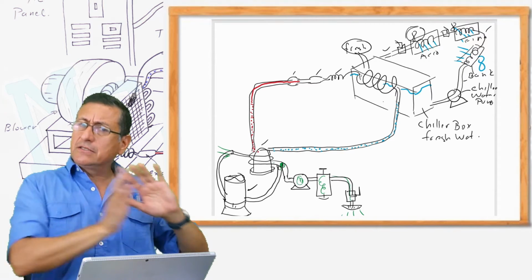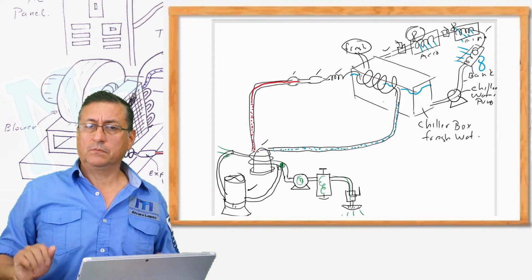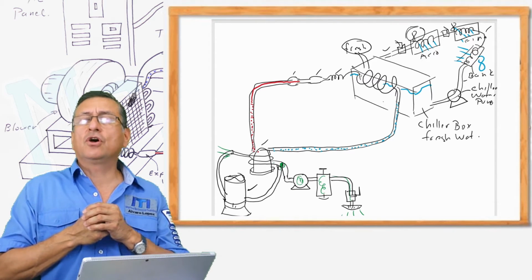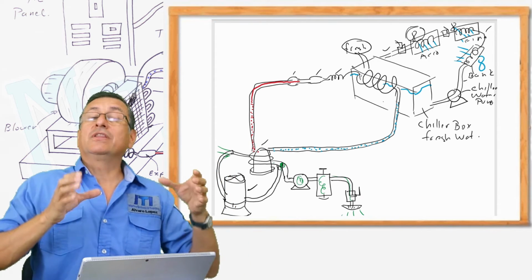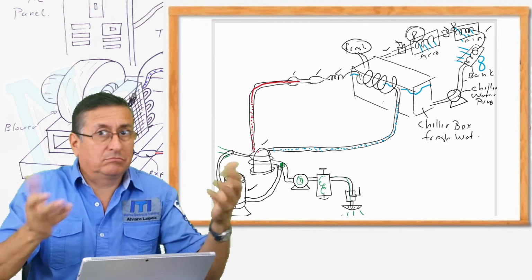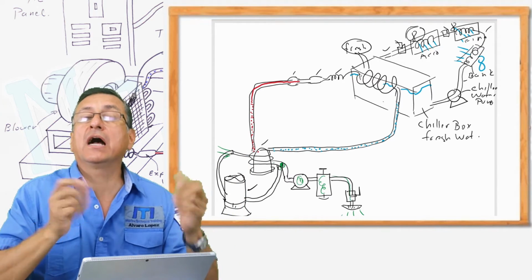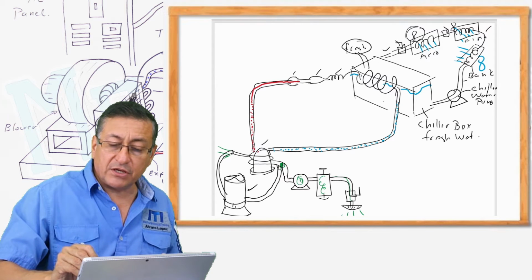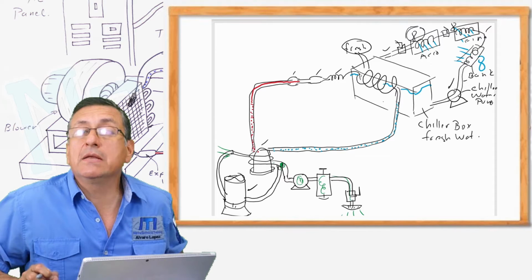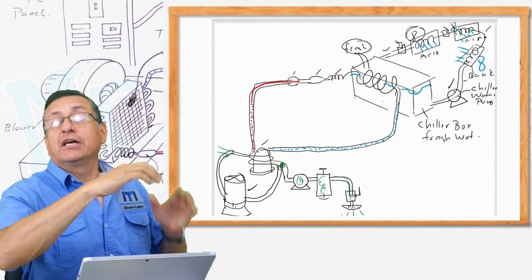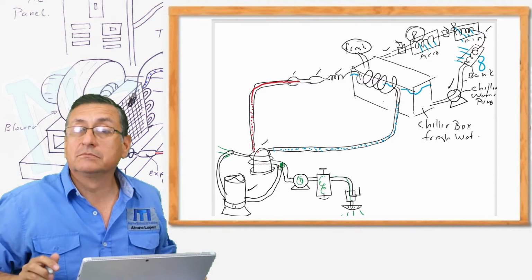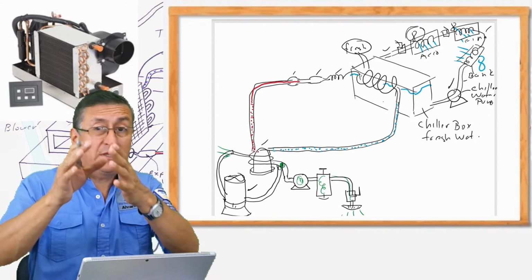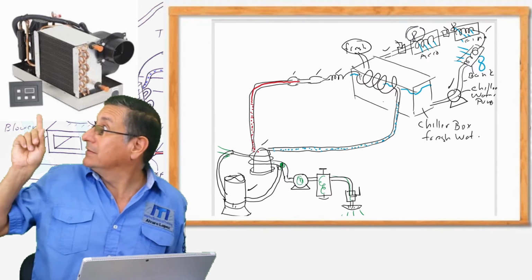In other words, the condenser is working with the traditional raw water system. All right? That's the same, no problem. But the evaporator right now is not with a fan. Right now, the evaporator is located inside a heat exchanger, but that heat exchanger is full of fresh water, and the fresh water enters that heat exchanger and goes out. The movement of that water is by means of this chiller fresh water pump, or circulating pump. After that, each department, each office has an air handler. It is a coil with fresh water inside and a fan in front of the coil. Simple. The air handler looks exactly like the typical evaporator, like this.